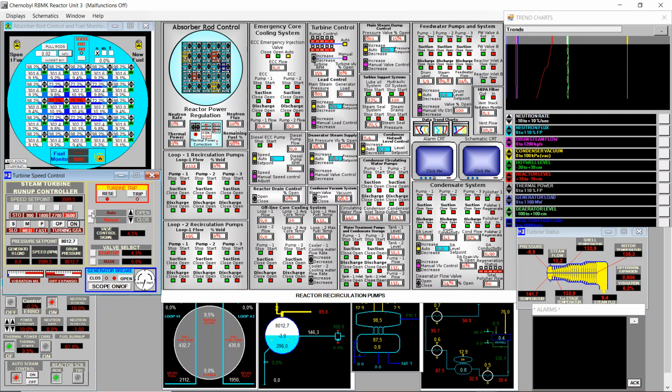Okay, we're almost there, and now I click auto. We see speed going down because the valve was closed at 3% at the moment of clicking auto, but now it will open the valve to go up to 3600, and at some moment it will stabilize these fluctuations. And yeah, now it's almost 5% of opening to go up. And now it's closing a bit to stabilize it, and you see now it's almost the nominal value.